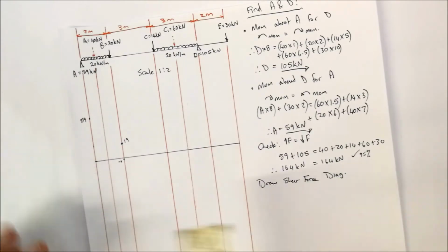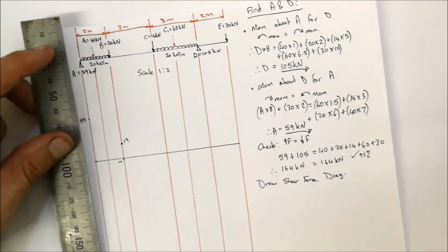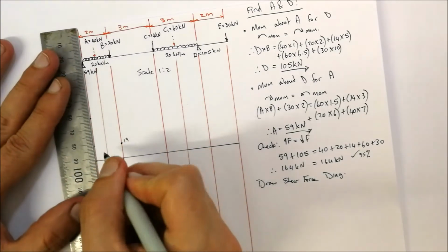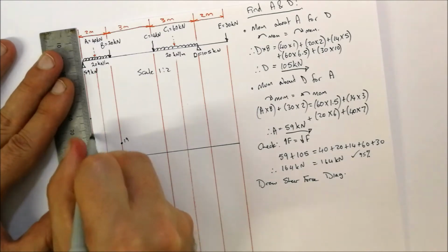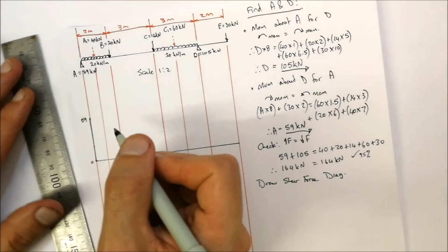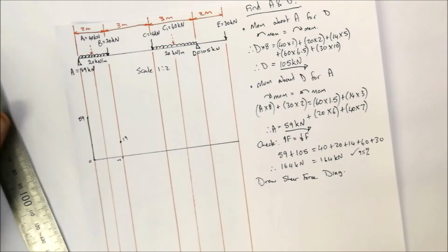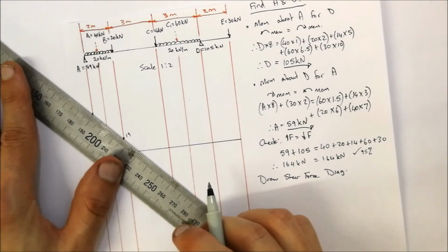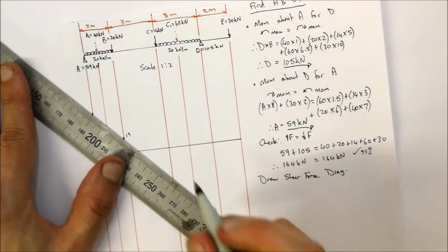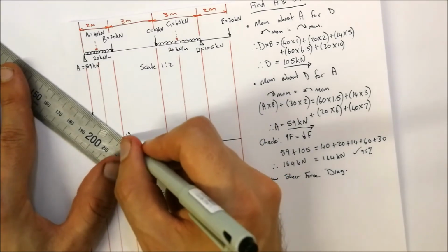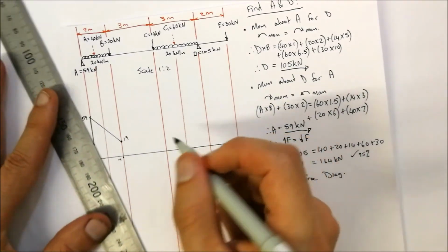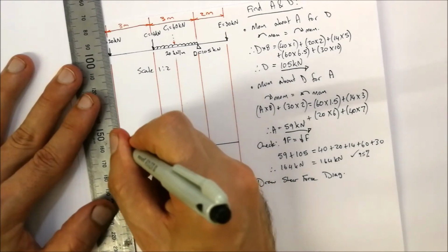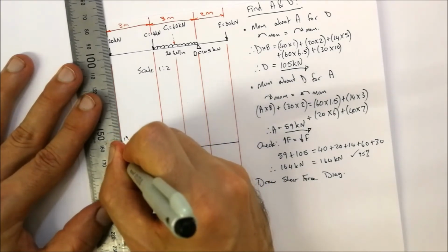Okay, so we can actually start just drawing our lines. So if we went from 0 to 59, you can join those dots over there. And from 59 we went across to 19. So our distributed loads are indicated with a diagonal line, so joining those two lines together over there. Okay, and then from 19 it went to minus 1, so we can draw that line down to there.